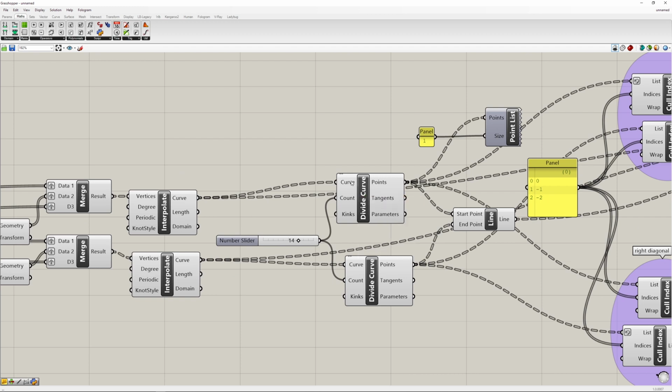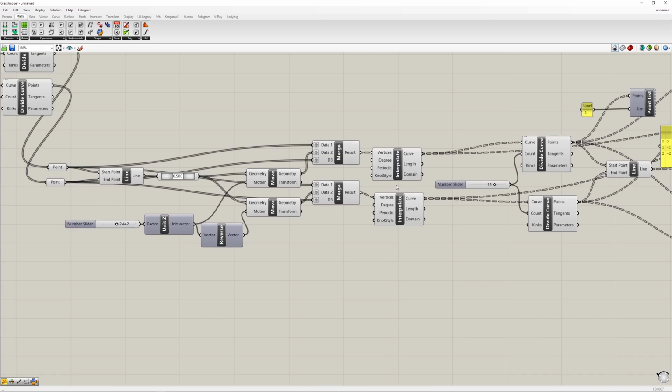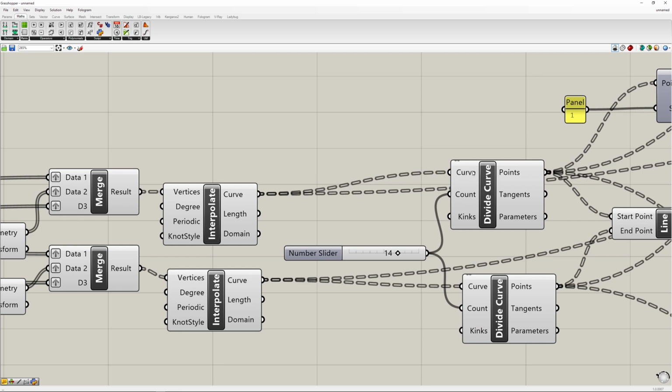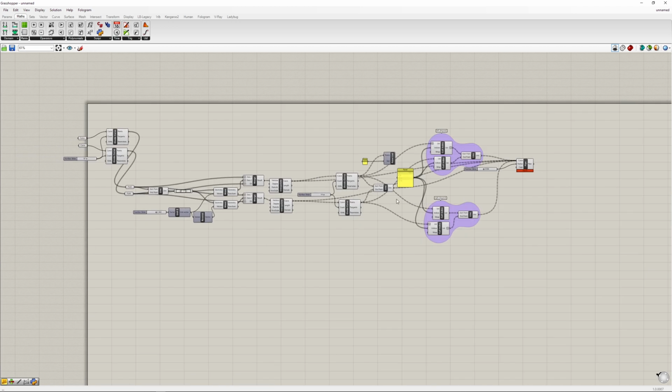A little tip I have for you, which was brought up in the workshop, is if you want to hide some of these cables because they're really busy, though I wouldn't recommend it, you can do so. Just go into wire display: right click on the wire you want to hide, choose wire display, and you can do faint for a really thin line, or you can turn it off altogether. It just gives a little wireless icon, showing you that it's actually connected to something. If you click on it, you can see what it's connected to. Personally, I just leave them all the way they are because it's a lot of work turning each wire off.